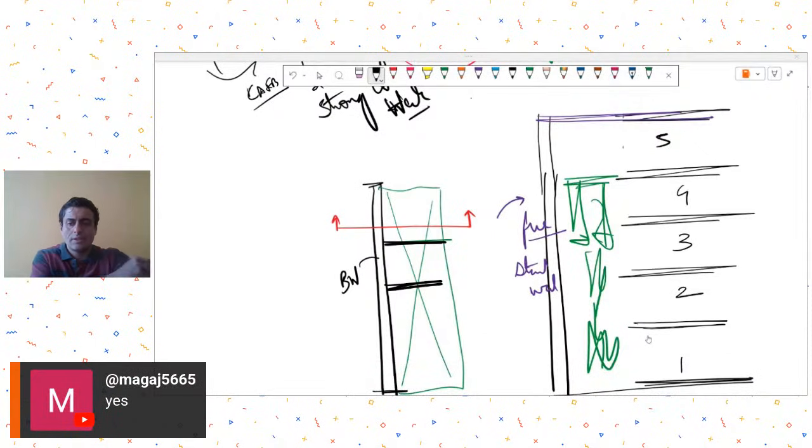Very nice. So see, 5 floors is a lot. First of all, you try to have a system where you are getting at least a tie after 2 or 3 levels. So you talk with your architect and tell them this difficulty, that over 5 levels not getting a tie is a lot. Of course, you can introduce some ties.